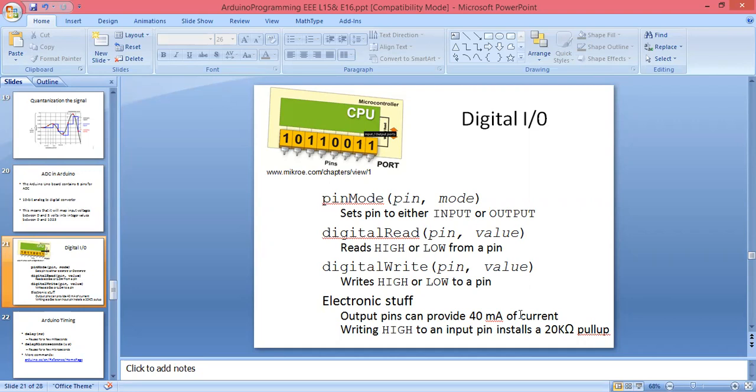and the Arduino board is connected to our desktop with USB, then the Arduino board will provide us 40 milliampere current. But we know that an LED is only capable of taking 20 milliampere.